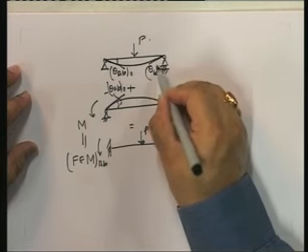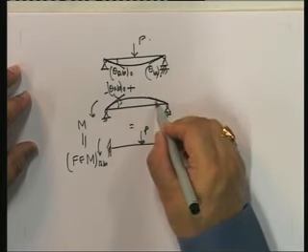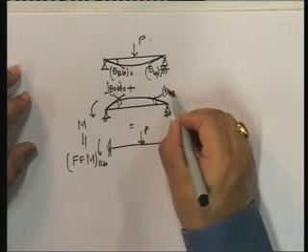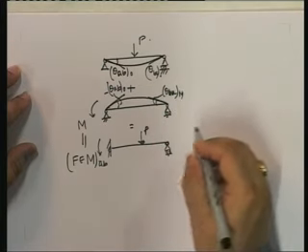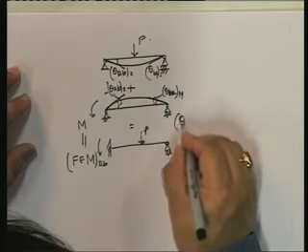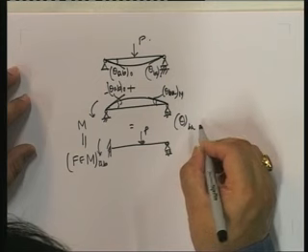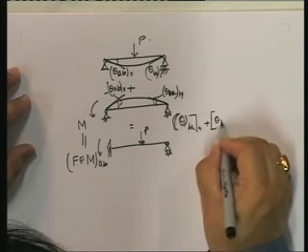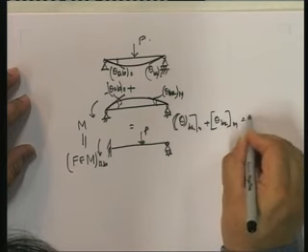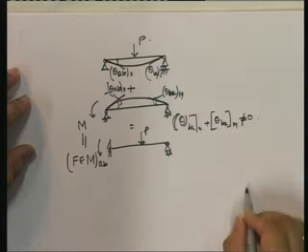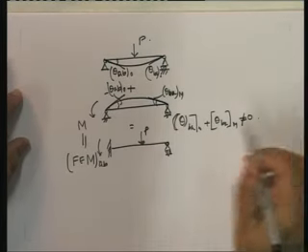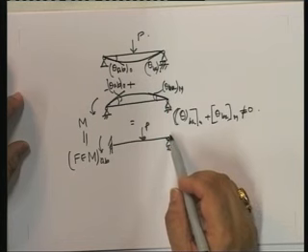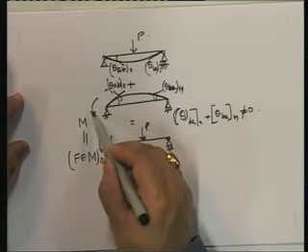theta BA 0, and this can be theta BA due to M. Nowhere does theta BA 0 plus theta BA due to the moment have to be equal to 0. No. Why? Because it's a hinge. Rotation can go anything. Only thing is we cannot apply a moment here, and I'm not applying a moment anywhere. Note that I'm only applying the moment here.